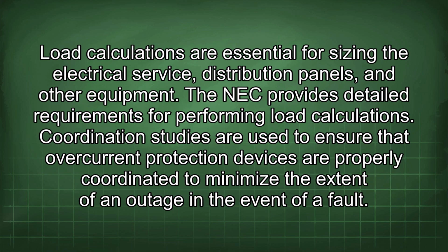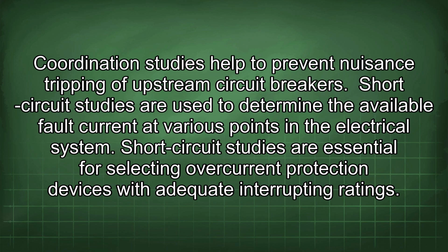Coordination studies are used to ensure that overcurrent protection devices are properly coordinated to minimize the extent of an outage in the event of a fault. Coordination studies help to prevent nuisance tripping of upstream circuit breakers.